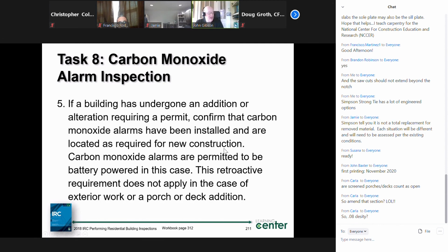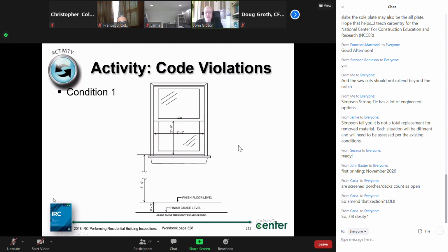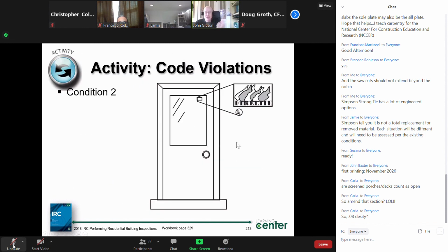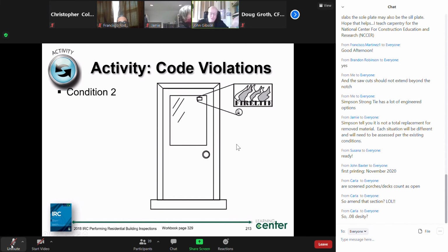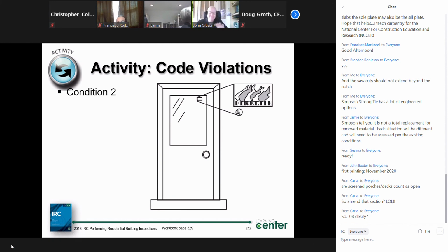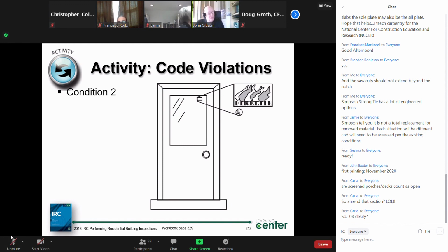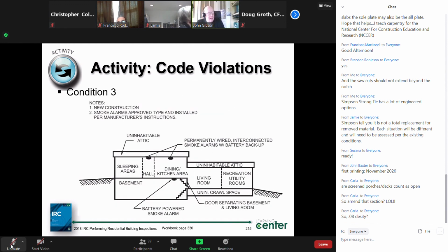And it has the alteration exemption where if I'm not removing those permanent fixtures, or interior finishes, I cannot require you to make them interconnected. However, that did get removed for smoke alarms. So 2021 code, guess what? Comes out in 2021 code. And there's practices for you.